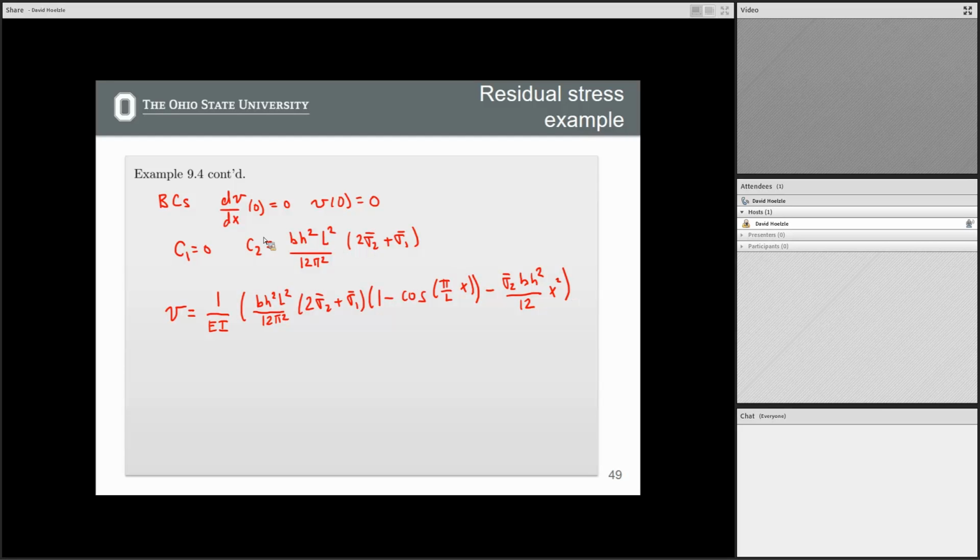So the next slide is going to show a plot, and it's going to show a plot with the case. All right, sigma 1 is equal to 350 megapascals. So keep in mind this is the highest stress seen in this part for configuration 1. Sigma 2 is going to equal to 100 megapascals. So remember, there's a stress relaxation when the part is released from the build plate, and this is the highest stress seen in the part measured experimentally. L is going to be equal to 45 millimeters.